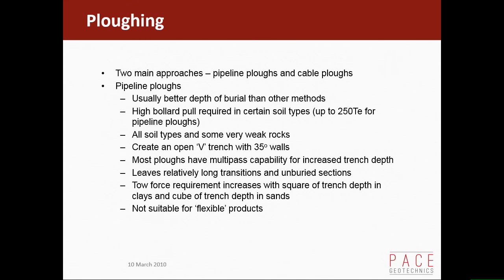Yeah. What depths are we looking at? For trenching. Yeah. From the shore end, if you go to West Africa, say, you probably trench most pipelines down to about 100 metres water depth. North Sea, you'll trench pretty well all old pipelines, all smaller diameter pipelines, up to say 400 metres water depth in the Norwegian Trench.